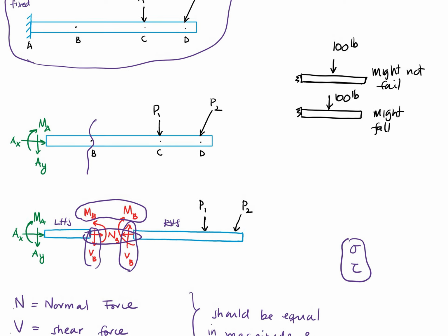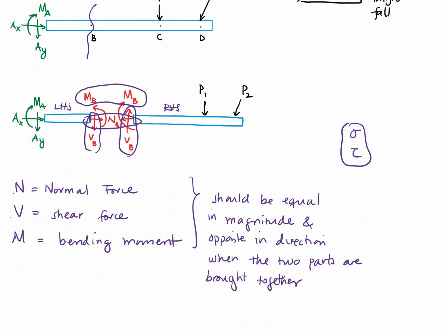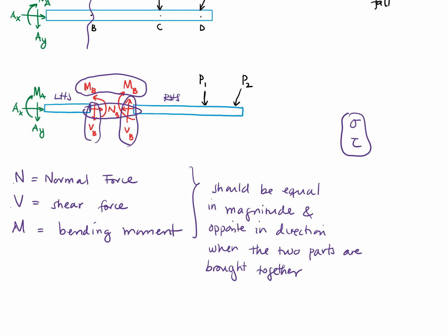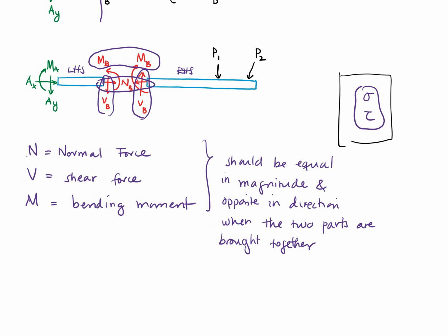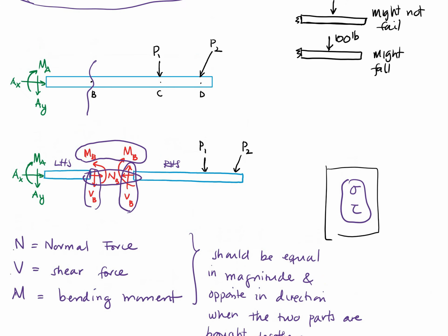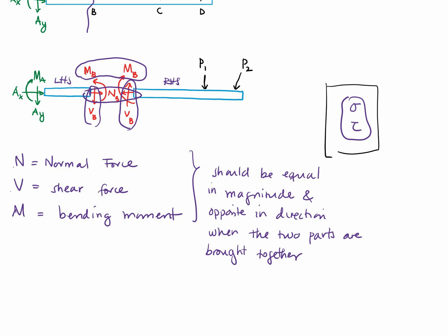So what we want to do is look at what the external force is doing on the inside as a first step. From there, we're going to start in strength of materials, worry about how the internal forces and loads affect the kind of member it is. So whenever we have an external load, we're making a cut at a certain point, we have three things going on.